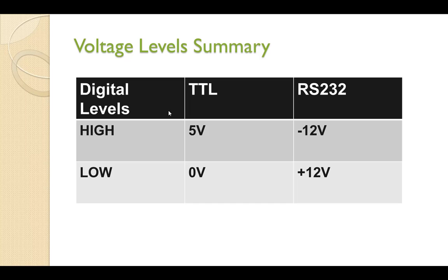When we are using this from the microcontroller to the PC, our PC works with RS232 logic. So if you want to communicate between the PC and the controller, we have to have level shifters. In the previous video, I explained to you that in the Nano board, we have an RS232 to TTL converter, right?